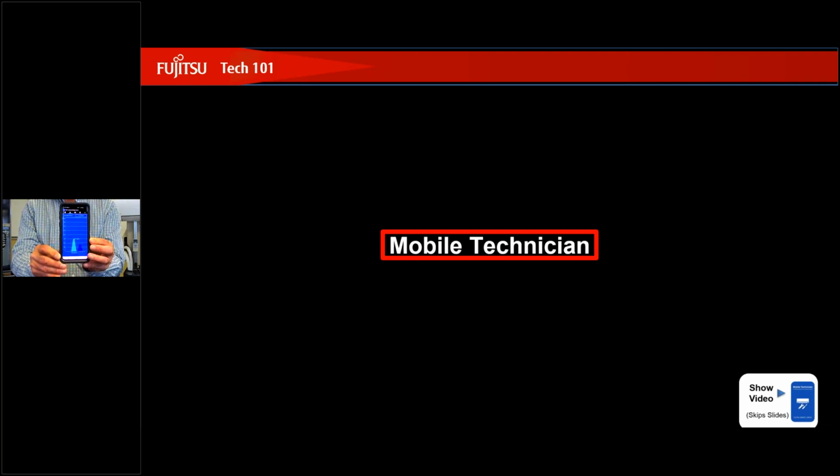But what this Wi-Fi analyzer does for you is when I do go to a job and we're having some connectivity issue between my equipment and their Wi-Fi system at home, I can use this to show what is on the system, what's the strength of their signal, and see if they actually don't have a strong enough signal. Our equipment will work fine, but their Wi-Fi connection is not strong enough to work with us, and that could be the root of the problem. Very, very important tool, okay?